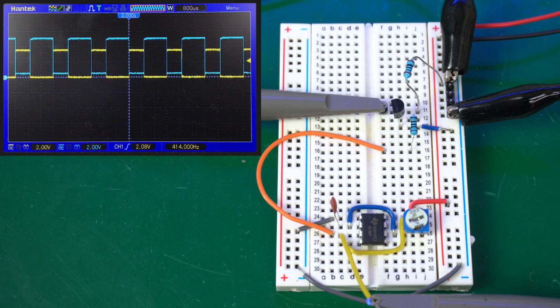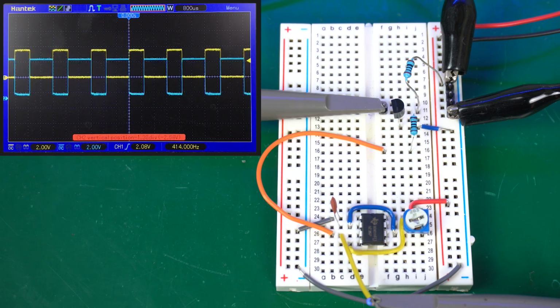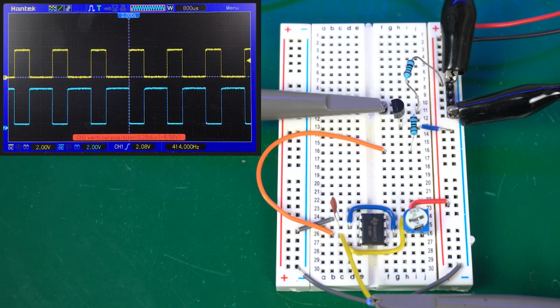I considered setting up a crystal oscillator and then some gates to shape the square signal, but in the end, I decided to go old school and set up a simple 555 timer. You really can't beat the simplicity of a small chip like that. And when I turned that on, perfect. Again, input square wave and output is a similar square wave, but inverted.